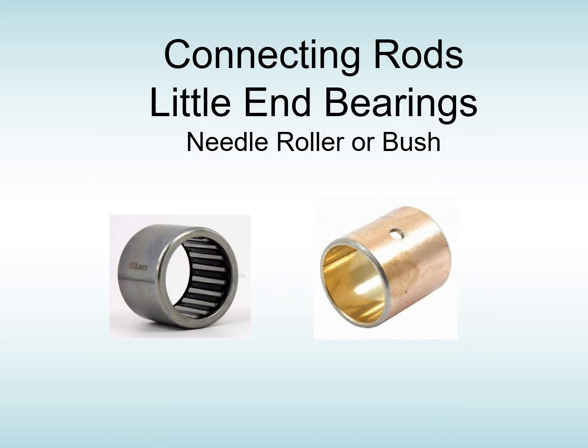Connecting rod little end bearings, as we've seen before. This one is bronze or phosphor bronze, and these ones are needle rollers. As I said before, they're generally used in the high pressure cylinders of, for example, a Grasso. On the low pressure side cylinders, you would have this bearing, and on the high pressure, you would have this bearing.